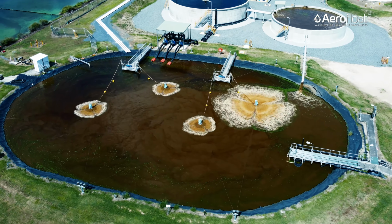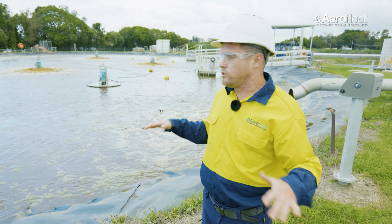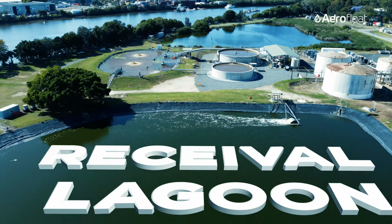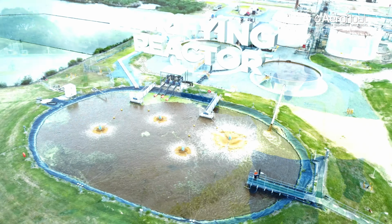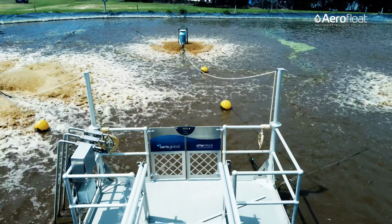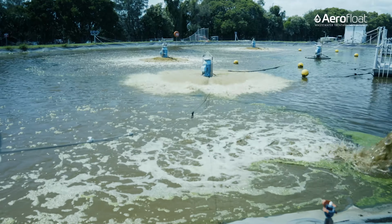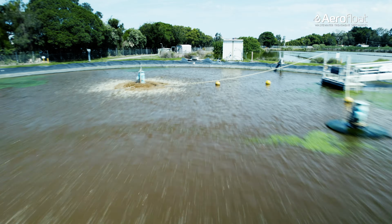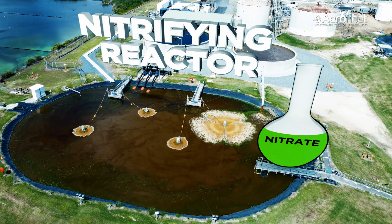So when we designed this plant, like any wastewater treatment plant on an existing site, you come in and you look around, you see what you can work with. So here we had this receiver lagoon, about 15 megalitres. We had this pond also here. We converted this into our nitrifying reactor, fitted it out with the pontoons, mooring cables, loaded it up with the aerators, and these aerators are coming on and off and controlling a DO set point on a PID. This nitrifying reactor is really doing the bulk of the work in the oxidizing of the ammonia to nitrate.